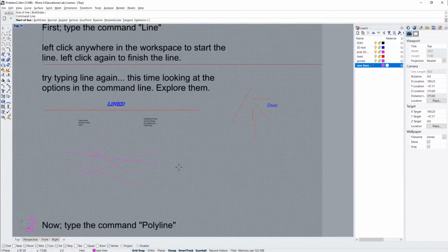Okay, so all these lines are crooked right now. That sucks. So if you click once and then you hold down the shift key, it's going to snap to either straight up and down or straight side to side. So that's by far the fastest way. I want to draw another one. I do my first click, I hold shift, and I drag the distance I want.